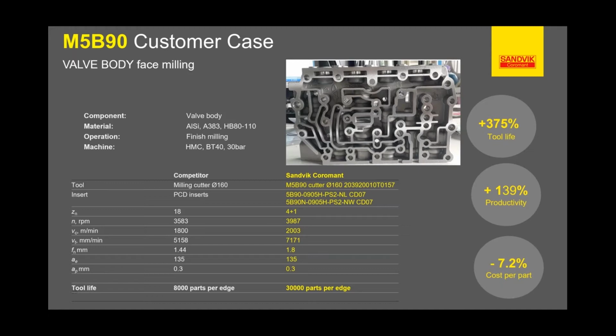Of course, we eliminated that deburring brush, so they don't even need it. So that being said, we could go up to 30,000 parts before there was enough of a burr that they thought, okay, we need to pull the cutter, we need to go in with a fresh one. So that's a significant increase. So tremendous cost savings, cycle time, cost per unit, etc.